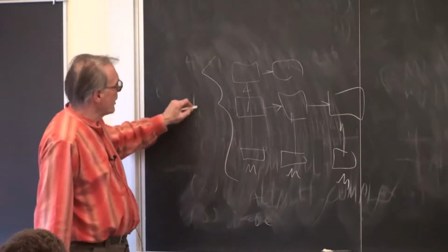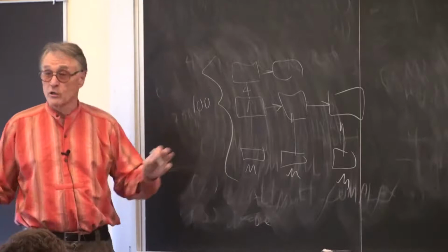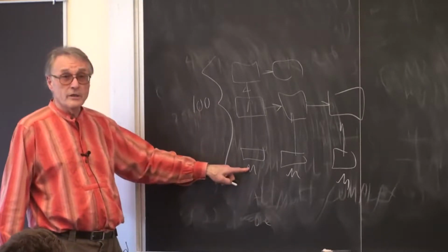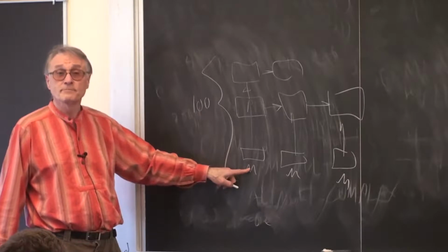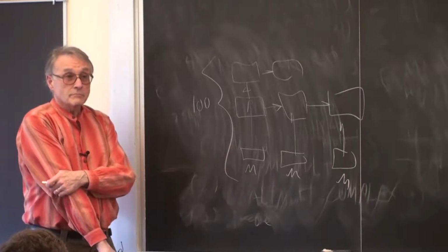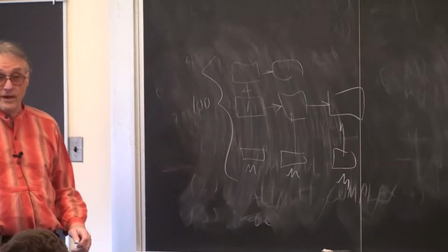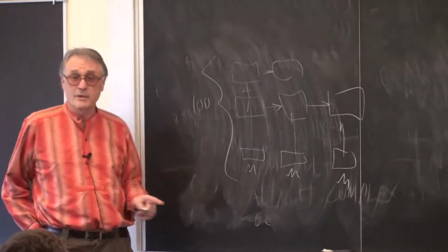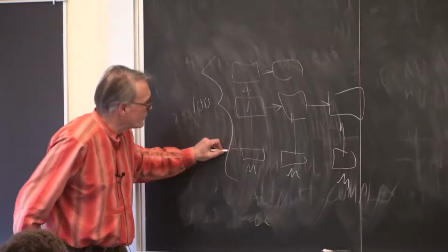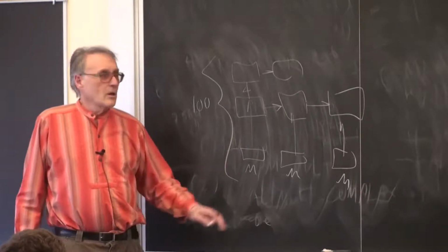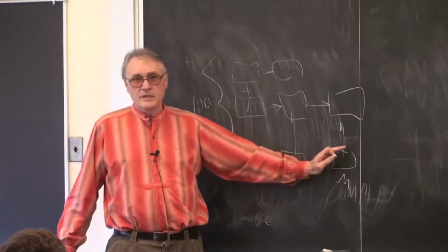So if there's 100 nodes, that uses all of the cycles. 100 nodes will fit in one M10K block. In fact, twice that much will fit in one M10K block. So maybe you should do 2 columns per M10K. So I'll talk about this in some detail next time.